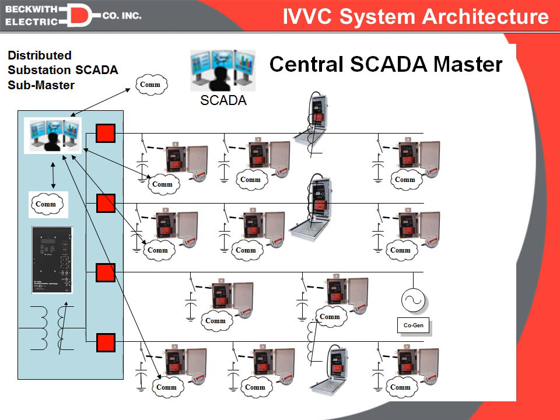The way the direct heartbeat is going to work is SCADA has to actually write a value into the timing register of each control. So again, if we want a 5-minute heartbeat, SCADA would write a value of 5 minutes into the timer. The control would start counting down, and if it reaches 0 before SCADA writes a new value into that timer, it will go out into local automatic even if it still does see valid communications.